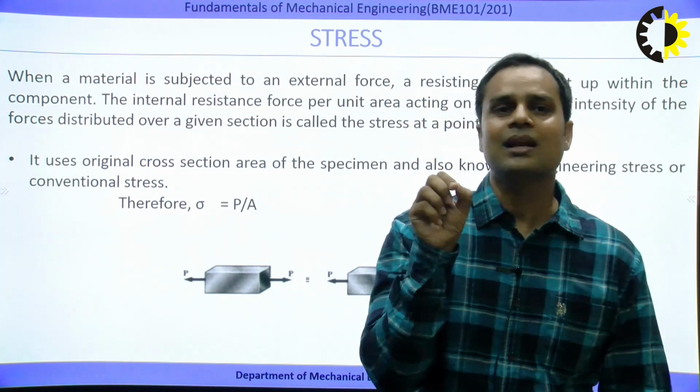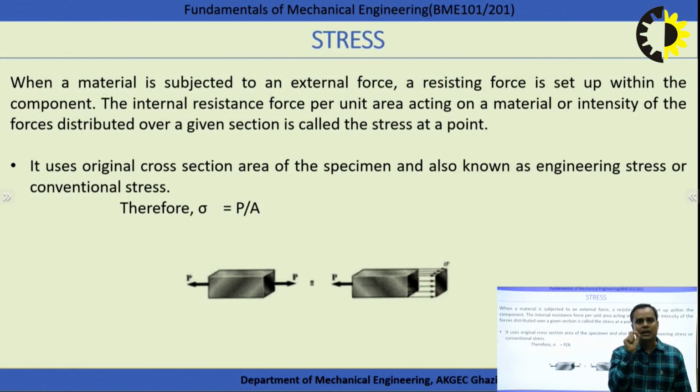It is the internal resistance force developed in a body against the deformation caused by the load. Simply, I am saying stress is the internal resistance force developed at a point against the deformation caused by the load. That is simply called stress. So generally stress is defined as load by area, internal resistance force per unit cross-section area.